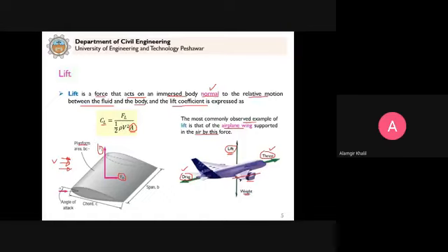What do we mean by the planform area? If you look at this object, it has this span b, but on this side you can see it is curved. So what dimension should we use? We use this chord c. And if you look at this plane from the top, what will appear? It will appear as just this dimension multiplied by this dimension, the span.